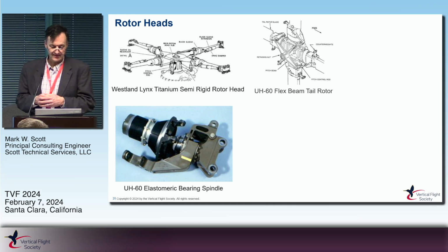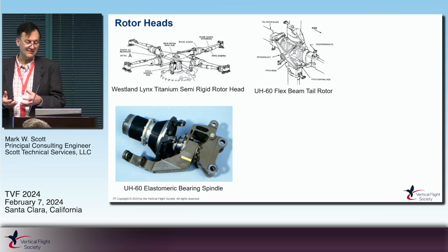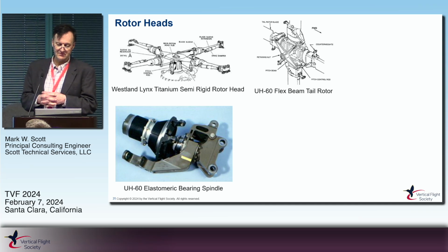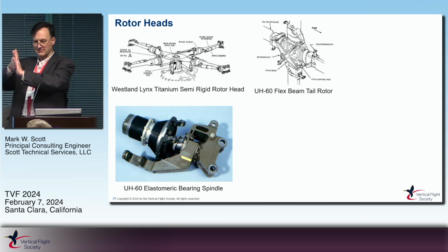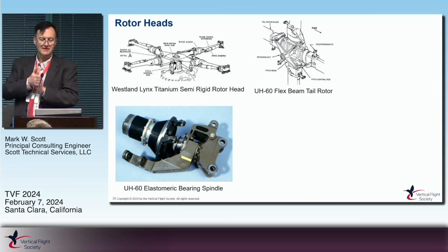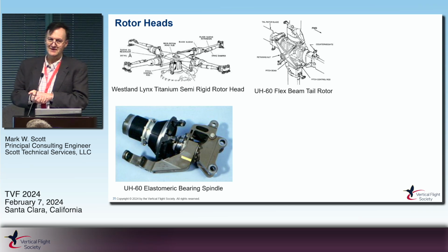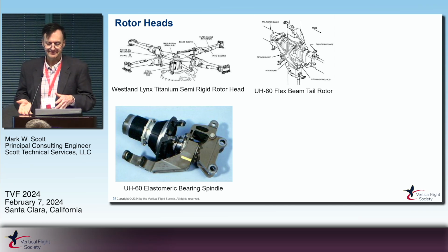Pretty amazing. But then composites, right? We're getting better at composites. With all the analysis we can do, the materials are getting better, materials are getting certified. So Sikorsky came up with the flex beam tail rotor, where you take two long paddles that are flexible, literally put them together like this or slightly out of plane, and they're flexible enough to take pitch, but they're very simple.